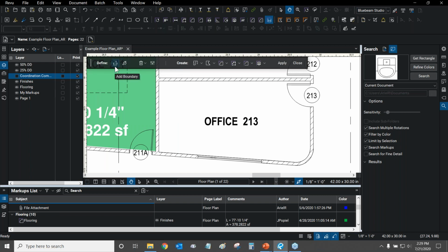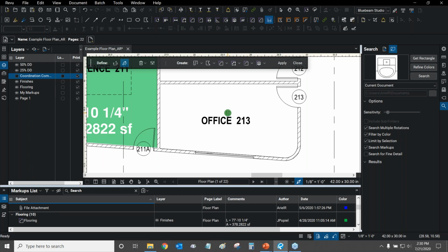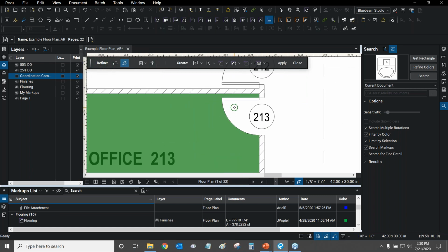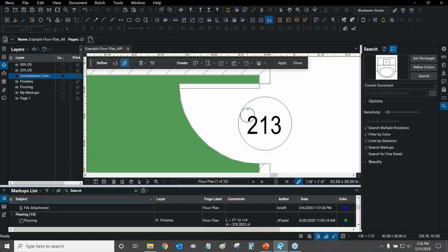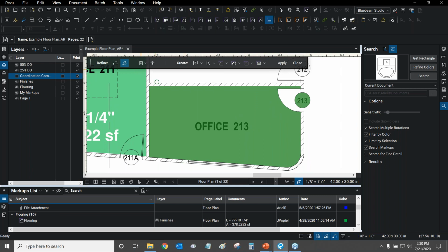Now, let's make a fill before we do a boundary, and I'll show you why boundaries are so useful. I'm just going to click and hold, and the fill will magically find lines and stop where they are. Now, this is good. The problem is that part of this room includes the part that the door is kind of blocking right here. So I need to make a boundary to tell the fill to go to the boundary and pass the door frame, and also pass this 203 circle. Because if I just make a fill here, it fills in the circle and it will not go past. Every single line right now will count as a barrier to the fill.